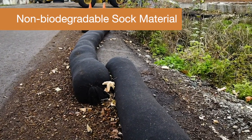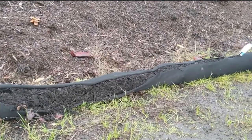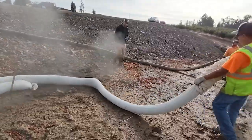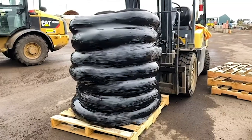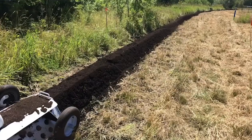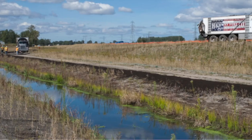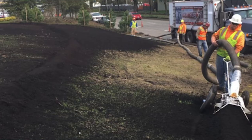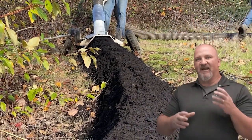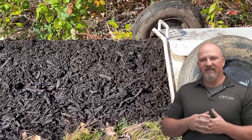The advantage of a compost sock is that at the end of the project, you slice open and get rid of the netting and pull the compost back onto the project. Compost socks are available in different diameters and can come pre-packaged on a pallet, or they can be blown in place on the project. Compost berms are berms of unconfined compost, so they don't have a netting. They're blown in place on the property, and it's essentially a berm that acts like a perimeter control that provides some filtration to dirty water leaving the site.